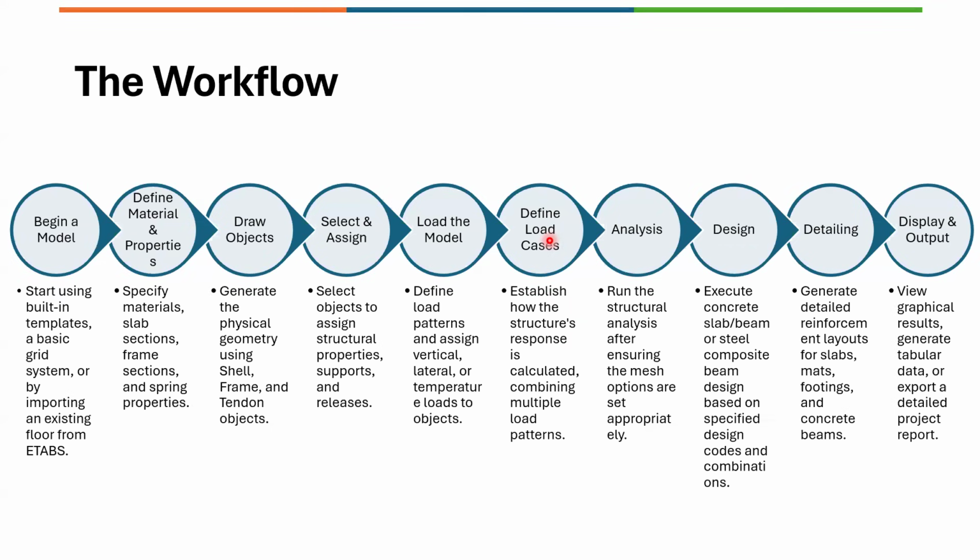So for all the load patterns through which loads will be transferred, the program automatically generates the load cases. If you want to create special cases by combining more than one load pattern, then you can do that as well. And then you can perform the analysis and you'll get the results for these cases. You can review those results and then you can perform the design of the members.